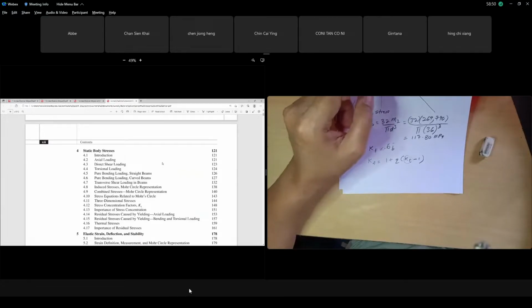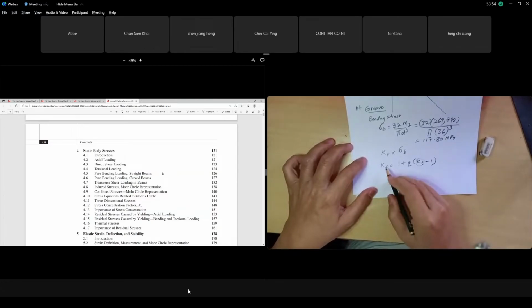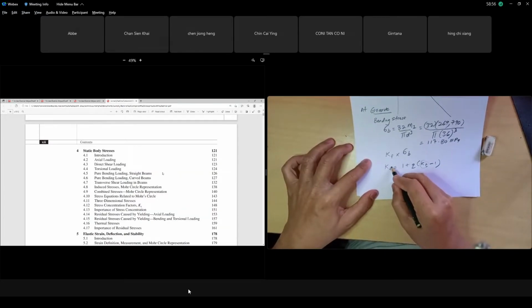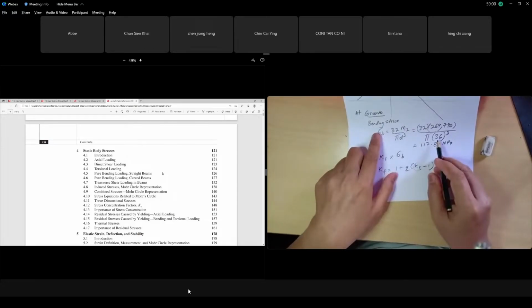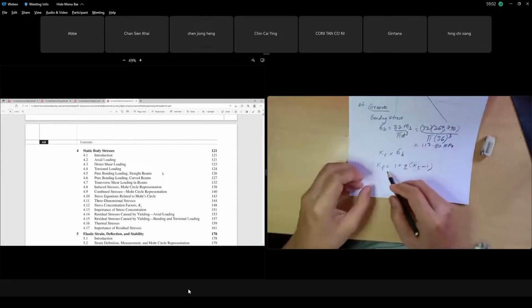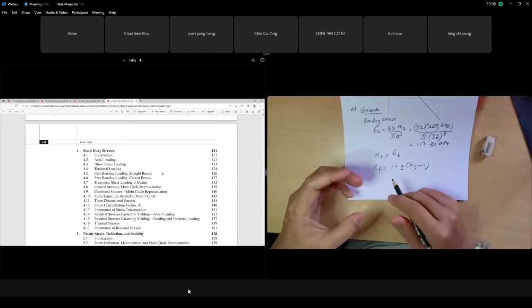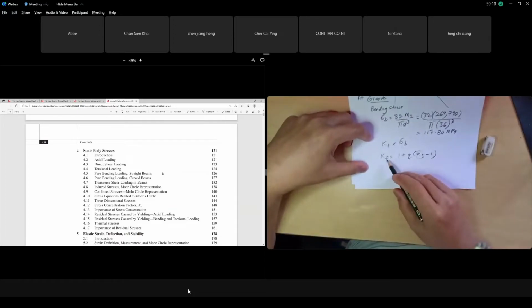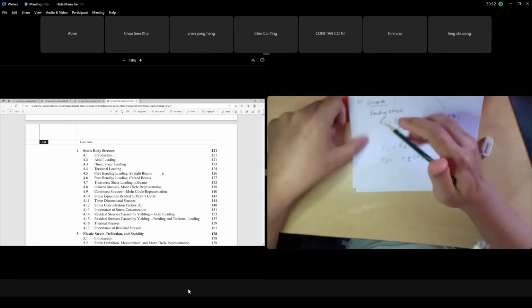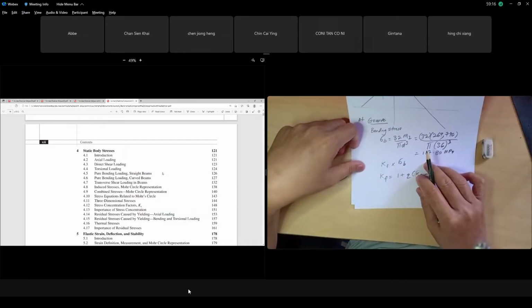Yes, doctor. Okay. We know the equation for the fatigue stress: we need to find Kf, then multiply Kf by the bending stress. For axial, we also need to find Kf axial times the axial stress. Torsion also, Kf torsion times the torsion stress. First we focus on the groove point, bending first, then we go for axial.